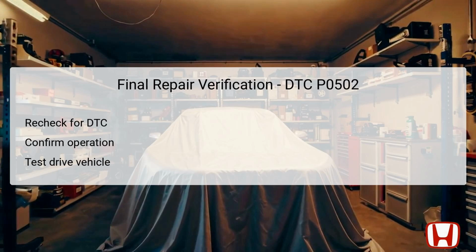During the test drive, the goal is to replicate driving conditions to see if the TCM now receives accurate signals from the CVT speed sensor without reporting errors. If the DTC does not return and the transmission operates smoothly, this indicates a successful repair. It's essential to document all findings and repairs made during this process for future reference and diagnostics.